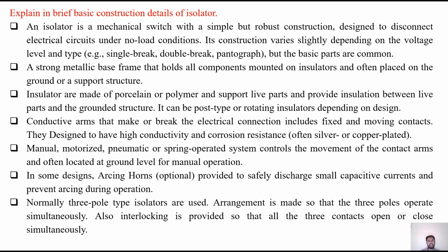A strong metallic base frame holds all the components, mounted on insulators and often placed on the ground or a support structure. Insulators are made of porcelain or polymer material and support live parts and provide insulation between live parts and the grounded structure. They can be post type or rotating insulators depending on the design.